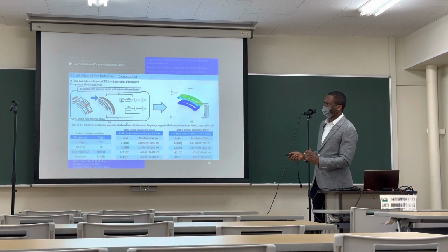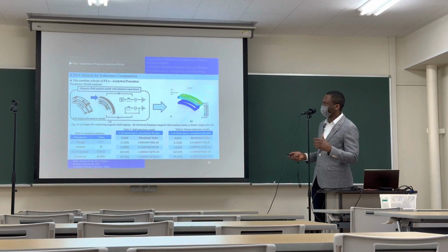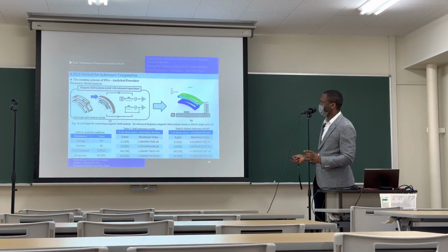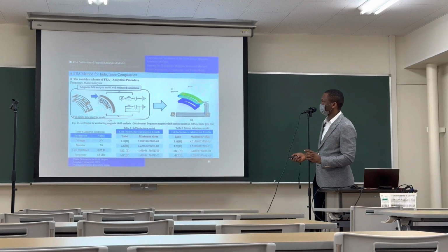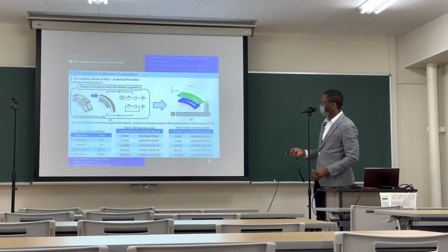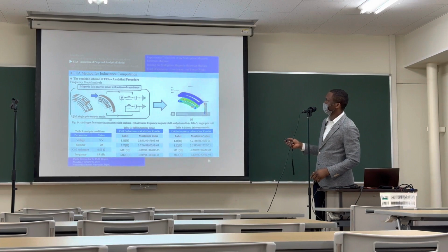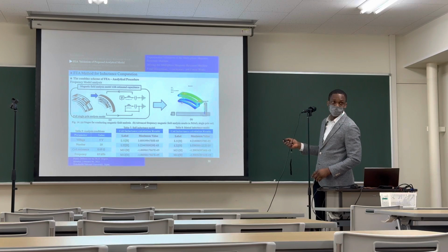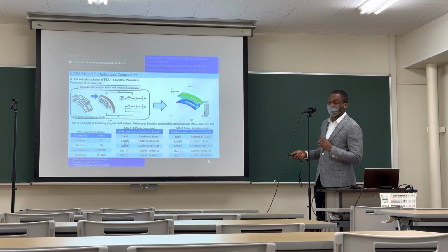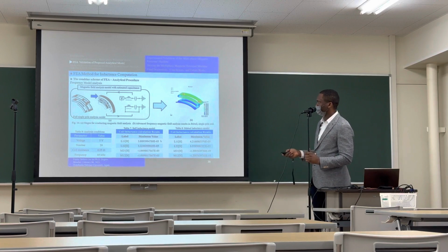At this stage, we can run a magnetic field analysis with the capacitance determined through the frequency. If you do that, you will have something like this. If you run it, you see that this is the main coil that is powered, and you see how the rotor coil is induced if it is properly done. And these are some typical values that we use during the simulation.